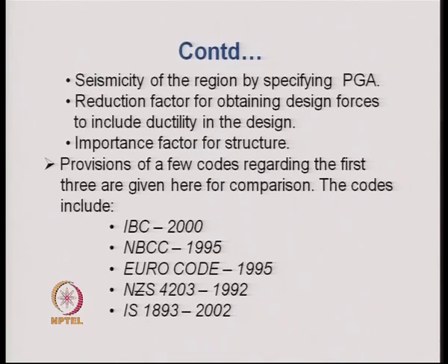The amount of displacement or excursion that the structures take after the yielding is governed by what is known as the ductility factor. Now, this ductility factor is in turn dependent on the reduction factor that is utilized for the design.